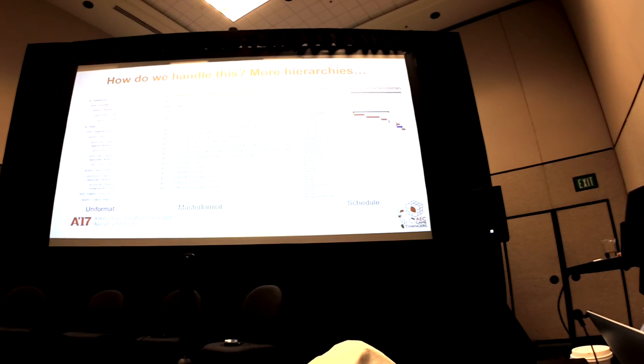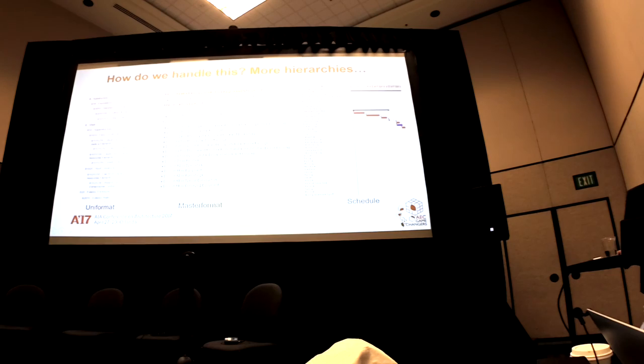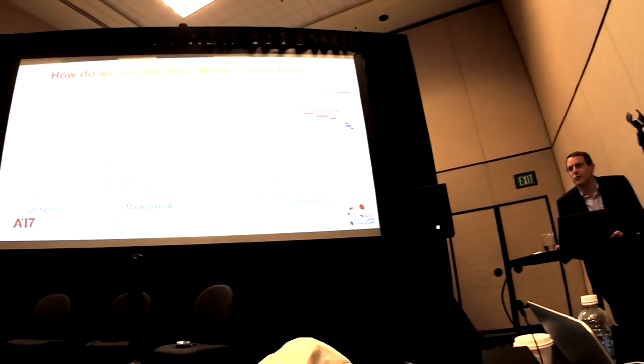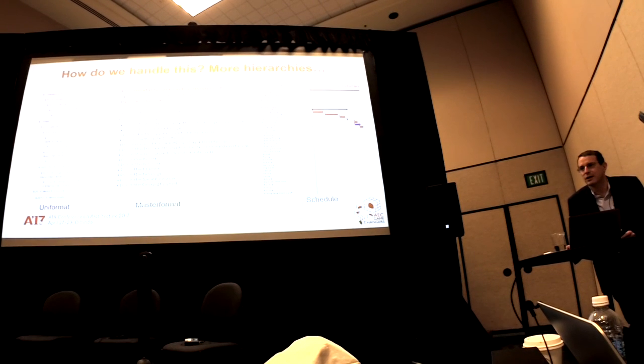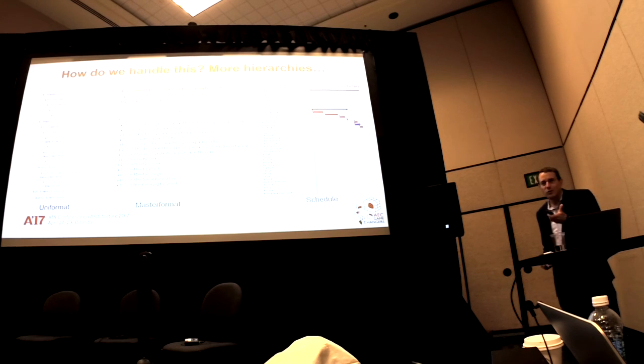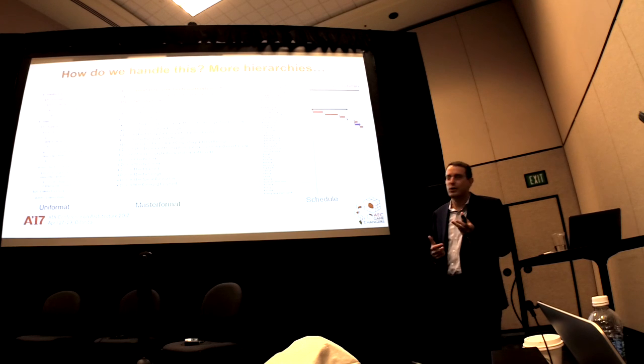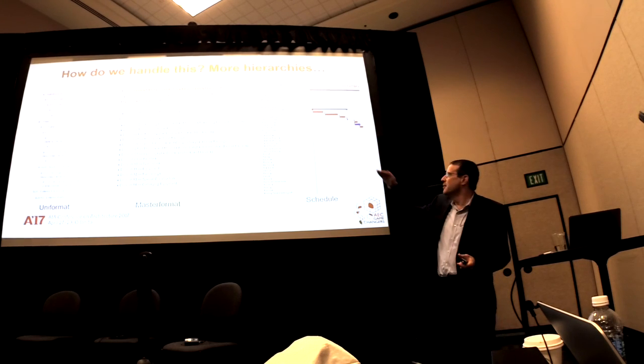How many of you know this? I think this is known by many of you. The ways that systems and even BIM objects are organized in UniFormat isn't one-to-one with the way systems are organized in MasterFormat. Your wood products, your wood systems are actually all over the place, in different assemblies. The wall systems and door systems and furniture all have wood products, or can. So the mapping between these isn't always one-to-one.